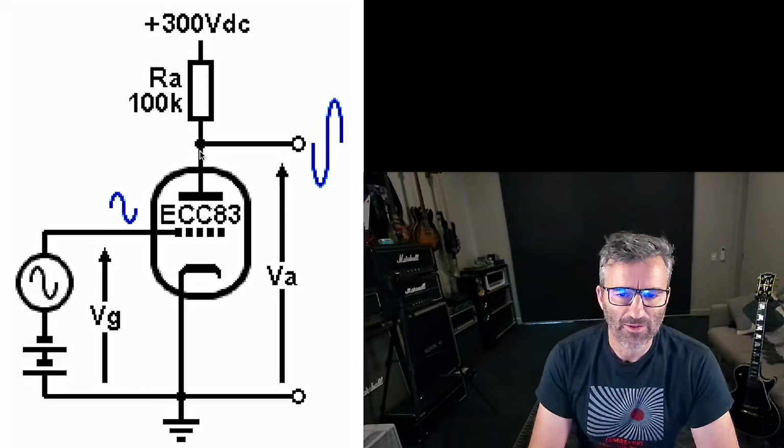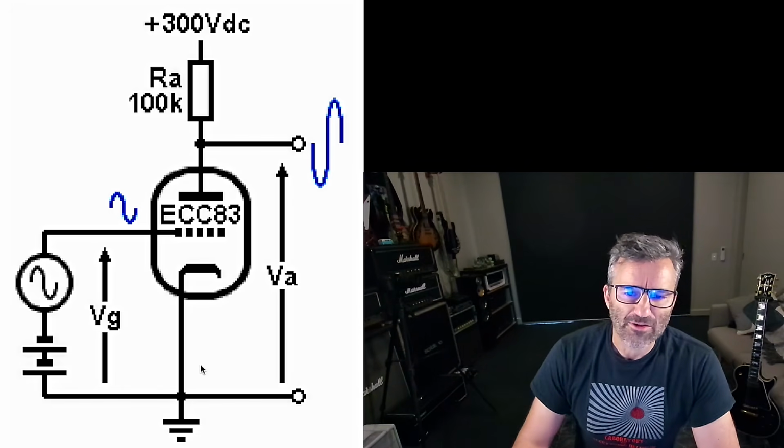So knowing that, which I'm sure you're familiar with respect to the power stage of your amp, think about that in terms of this preamp tube. Now, you never see this implemented like this in a guitar amp, although you could, right? You could have a 12AX7 just like this, tie the cathode directly to ground, but if you did that, you'd need to have a negative DC voltage available to put on your grid, right? So that you could bias the stage of the tube correctly.